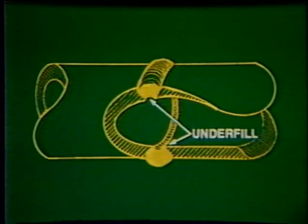On pipe welds, underfill is most common at the root and is referred to as internal root concavity or as suckback. When welding in the overhead position, a root opening that is too wide or too hot a joint will cause the puddle to sag in and become concave during solidification.